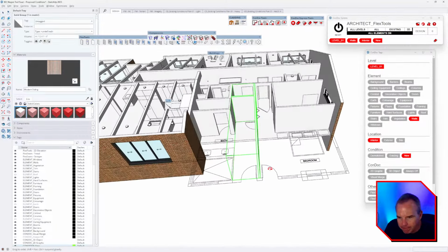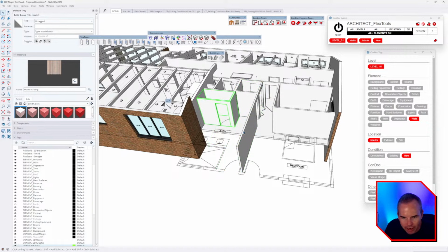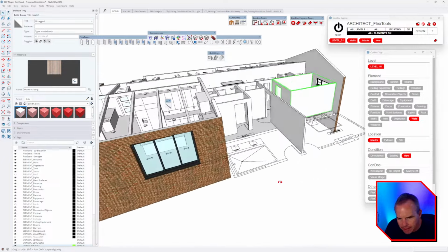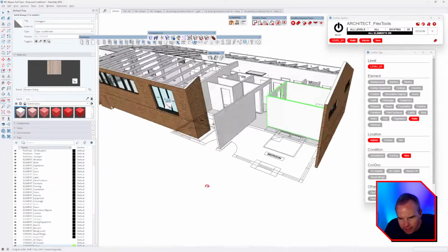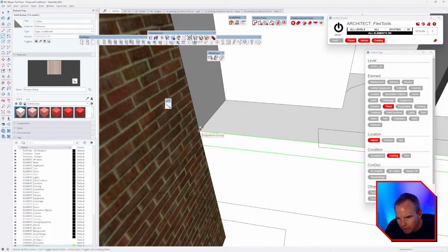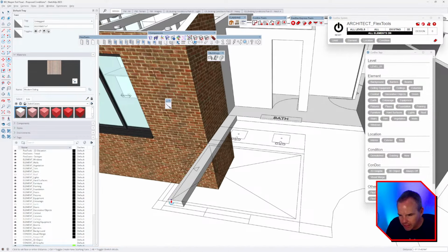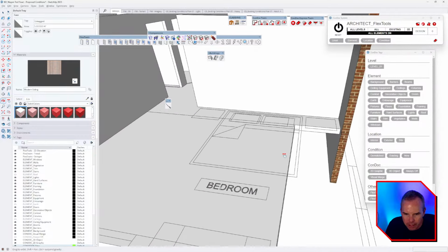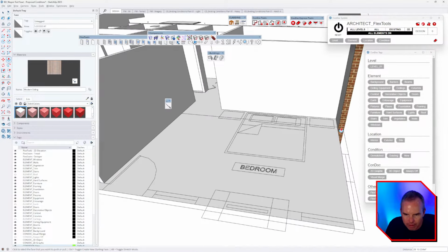But all right, so we got our walls. These are going to be level 1 walls, interior new, like that. All right, and this will be a pretty easy one. We can make a new floor. So I put my cursor on here with the rectangle tool, snap to that wall, and pull this floor out like this. I'm just going to pull it all the way out and then pull it across like that.